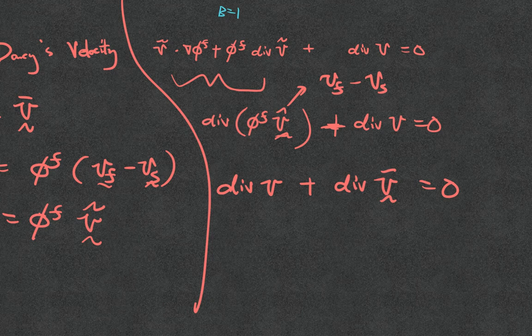Now, we have talked all the time about the balance law for the balance of mass for the compressible flow. How about the balance of linear momentum? How about the balance of energy? This also needs to be changed, because in this particular case the effective stress principle also needs to be generalized. Previously, what we covered is Terzaghi's effective stress principle, which applies to soil very well. It doesn't really apply to soft material or even rock that well, okay?